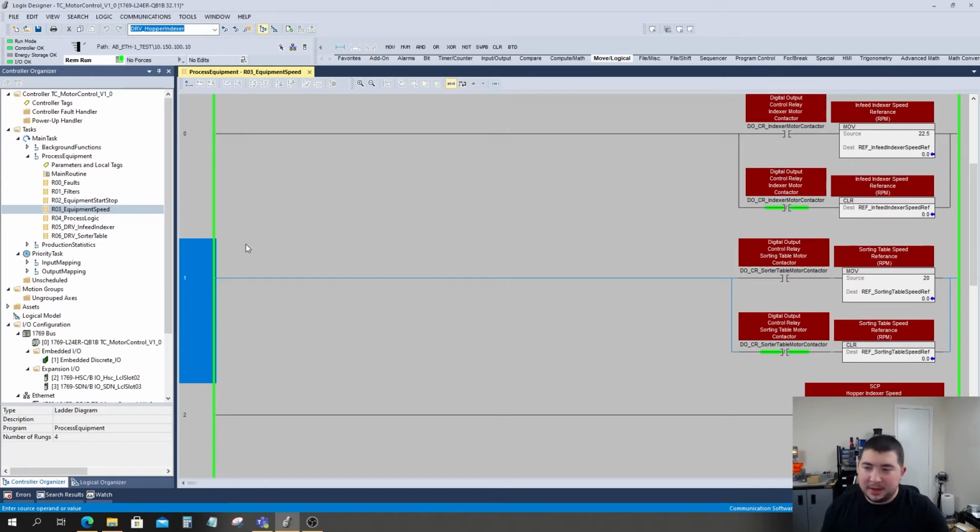We can say, okay, well, half a second ramp up isn't quite good enough. Maybe we can just change it to a quarter of a second, or if it needs to be longer, we can make it a second. Whereas right now, it's currently based on a potentiometer where you're probably just going to have to eyeball it and hope it works. By doing it in the program, we can be a little bit more precise and know that our ramp rate is what we expect it to be.